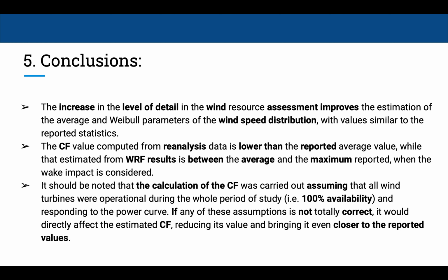This is an important remark: the calculation that we have done of the capacity factor was done assuming that all the wind turbines were operational during the whole period and responding to the power curve. If any of these assumptions is not totally correct, it will directly affect the estimated capacity factor, reducing its value and bringing it even closer to the reported one.